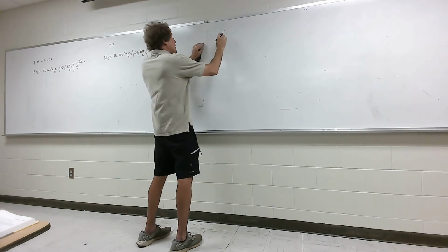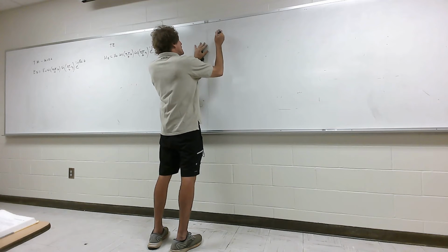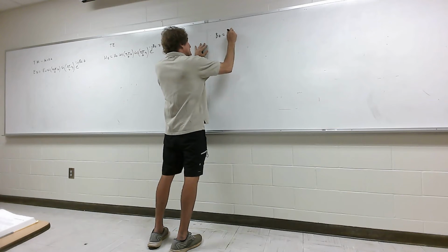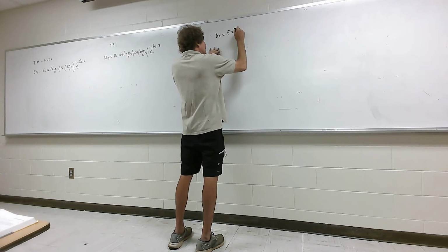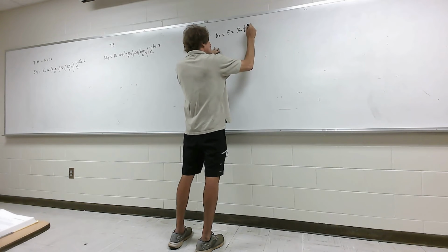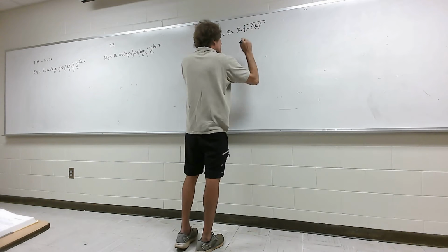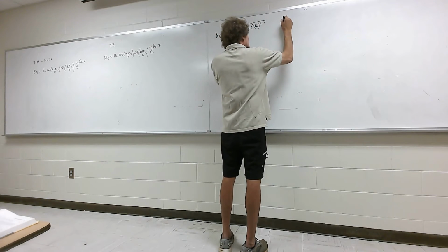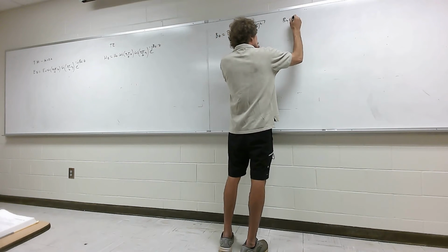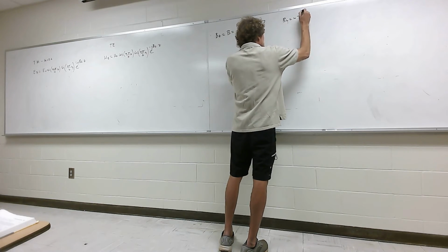Here's what's common to all. First, we talk about beta z, which is the waveguide's beta. That's simply beta unguided times the square root of 1 minus fc over f, squared. And of course, beta unguided is just equal to omega times the square root of mu epsilon.